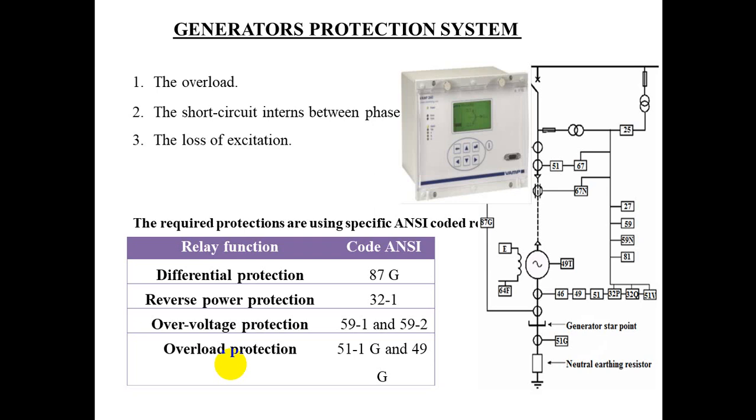Protection against vibration. Vibration detectors are usually mounted on the bearing pedestals. The detectors consist of a coil mounted on a spring between U-shaped permanent magnets. The voltage output from the coil, which is proportional to the degree of vibration, is passed into integrating circuits and then into an indicating instrument.